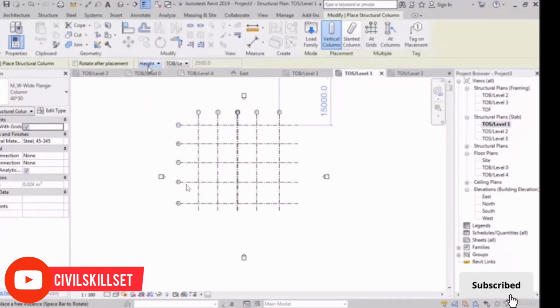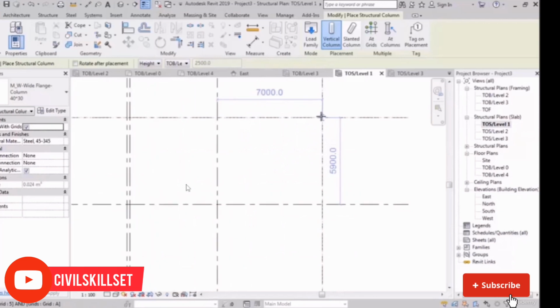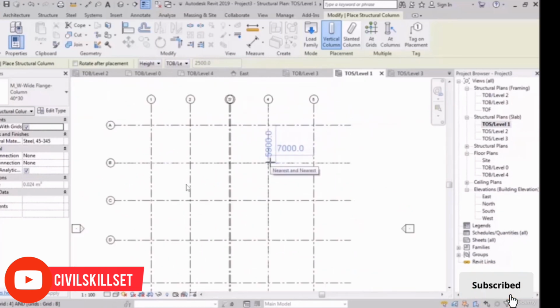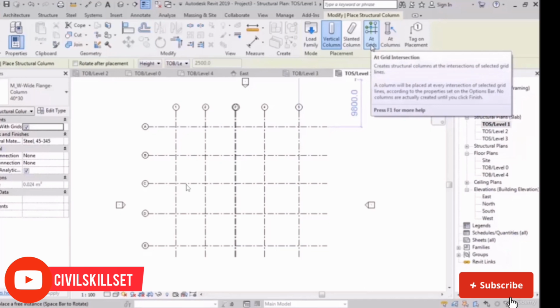We are paying attention to the 2 points: vertical column, and this should be height. All right. Now, in order to place these columns, we can do it one by one in the places where the grids cross, just like that. We can do it manually. We can also use a tool called Add Grids. What does it do? Well, Add Grids creates structural columns at the intersections of the selected grid lines. Right.